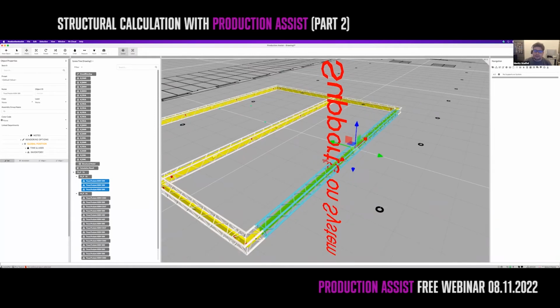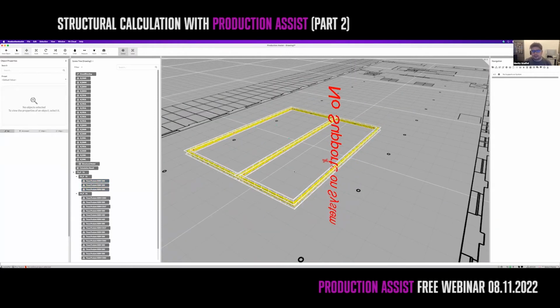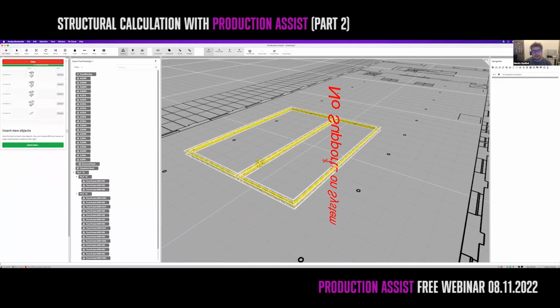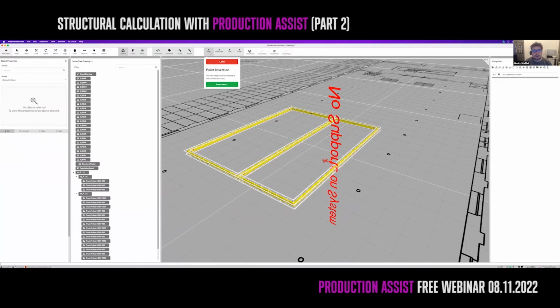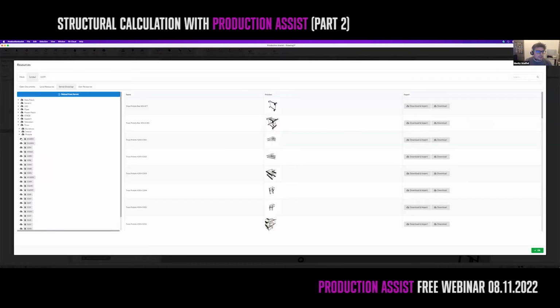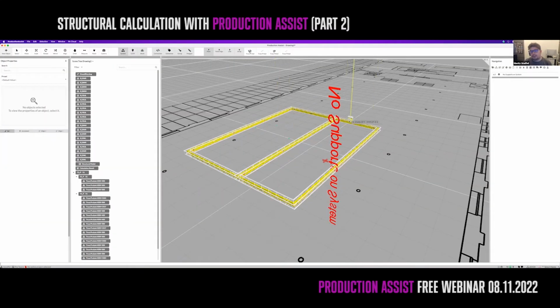In order to solve this problem, well, we need some hoist, so something that actually puts this up and puts it in the roof. So what I'm doing is I'm using the new object, selecting the point insertion, and using the right symbol for this. So I will go for the supports and I will choose some of the default hoists that we have. So for example, like a 320 kilogram D8 plus motor. Selecting this will bring me to the actual hoist, and then I just can click and insert it in here.